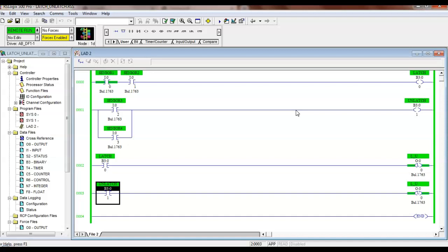It doesn't get rid of the power relays. It gets rid of the what? The control relays. So I could use the output to pick up a contactor. In fact, we could look at the Amatrol line and you see they got motors out there, but the big PLC can't run the motor, but the PLC can pick up a power relay that runs the motor. But then we got all the decisions going.